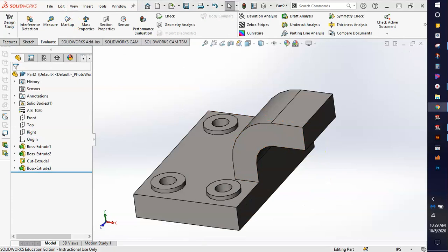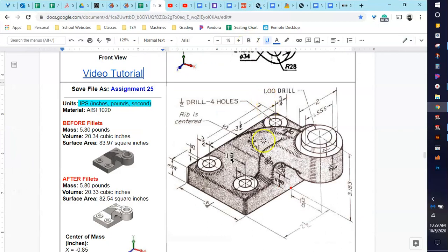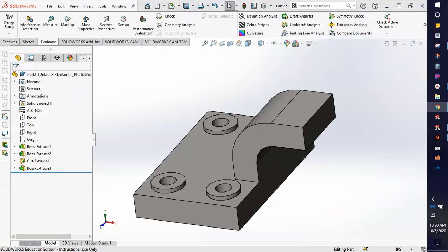So I'm going to pull this back over here to kind of explain the next portion. And the next portion is going to be the part where we're going to have to make a plane. So you can see right here that this cylinder doesn't necessarily have a measurement of how far up it is or how far down it is. So a lot of people would just sketch right on the top and either try to do the math of dividing this, or they'd make a mid-plane from this flat surface to the top and this flat surface to the bottom, draw right in the middle, and they would extrude this. But what they would run into is the problem that you would not get this measurement correct. So in order to get this measurement correct, we are just going to make a plane that's floating all the way up here at the top at that measurement and then work our way down. Okay, so I'm going to pull this to the side.